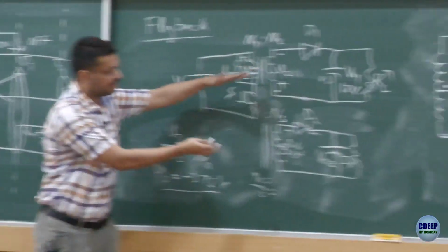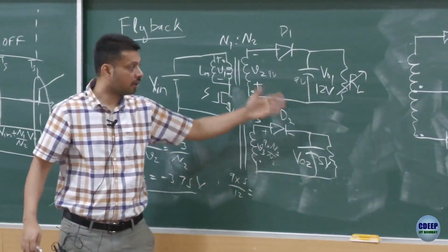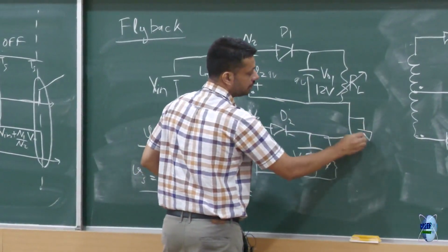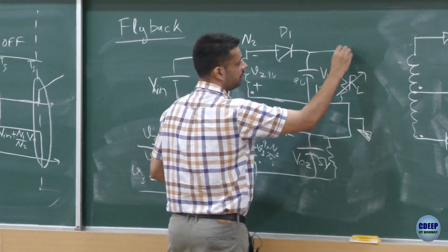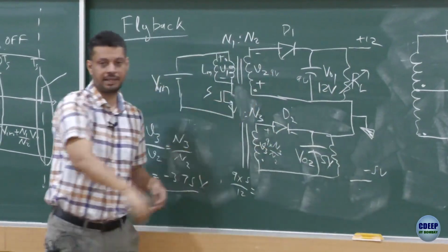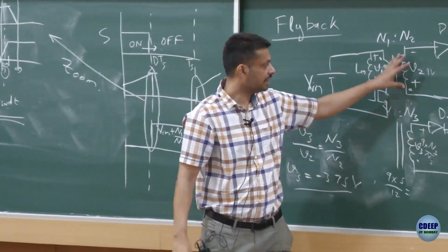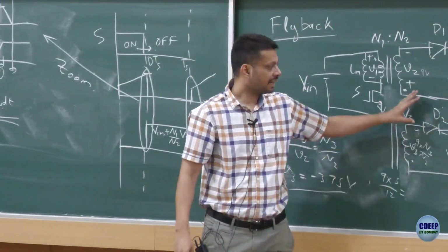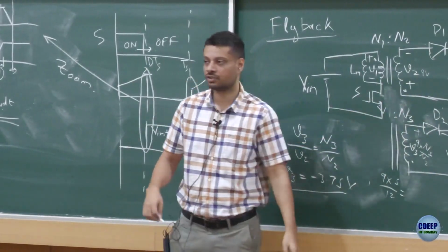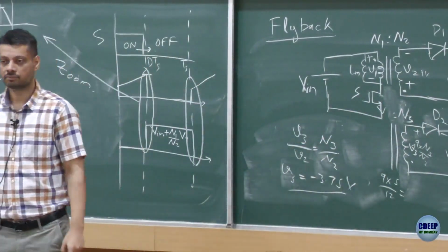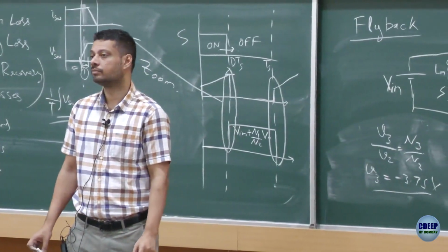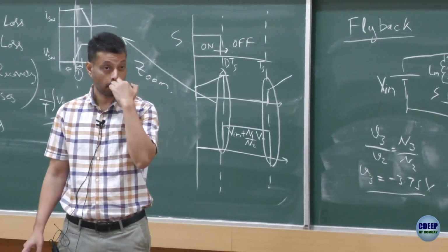It's the same circuit, I have just connected them together. So you can connect like this, or physically what you can do is connect this output to this one and ground it, and you will get now plus 12 and here minus 5 volt. So it's one and the same thing, right. You still require the same number of turns, it's just how you connect the 2 turns, so you can represent it the way it is shown on the left side, or the way it's shown in the middle one. Okay, any more questions?